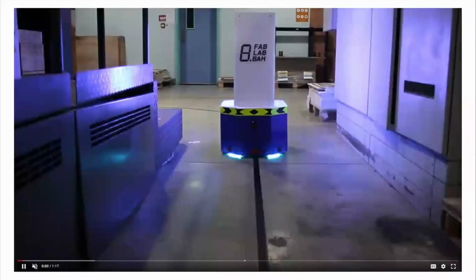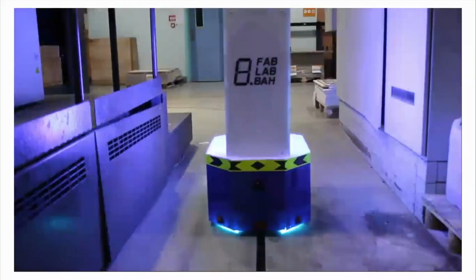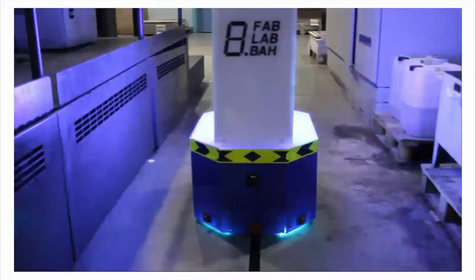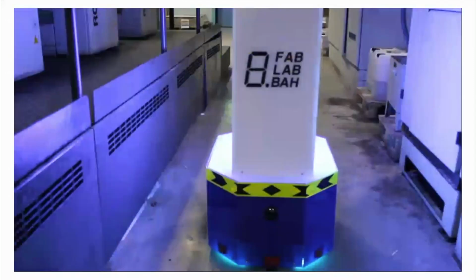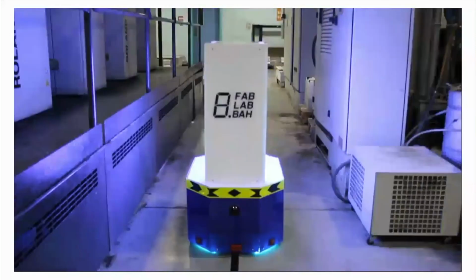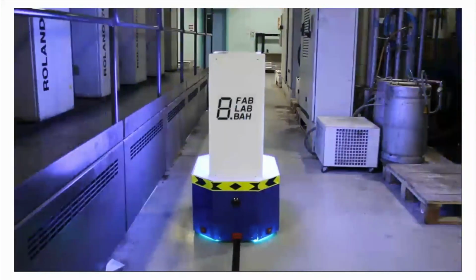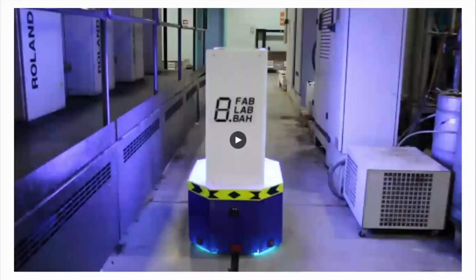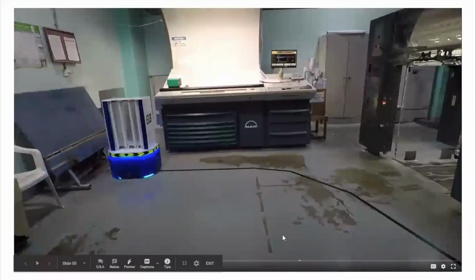Using the joystick is a very handy tool because in most cases you want to override the robot. Let's say the robot goes on a wrong routine, or skips the line, or malfunctions, there is a bug or something. You need to have the ability to take over and control the robot yourself as a human. And that's what we did. We made an algorithm so that while it's working in line follower mode, it breaks the program if we press the emergency switch on the joystick. It gives me the full power of overriding the robot.